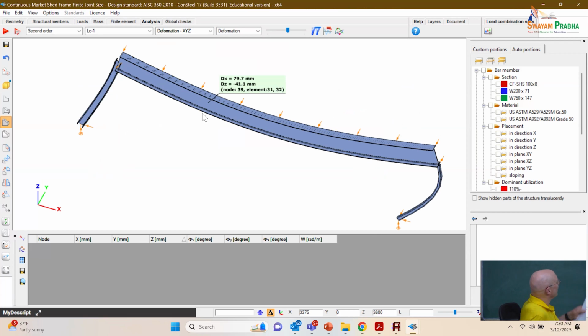So we can see already that the gamma critical was decreased. What's the buckling mode? We can see there's a lot of non-sway, or basically non-sway bending, we'll call it, in the HSS section. Now if we do a check of the wide flange section there,